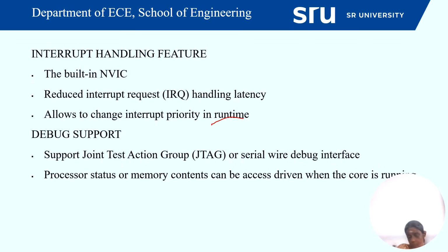In something like the 8051, the order of priority is given to the interrupts. Beyond that priority level, the Cortex architecture is able to change the priority of the interrupt during runtime, when it is in execution. Even during processing time it is able to change the priority order.